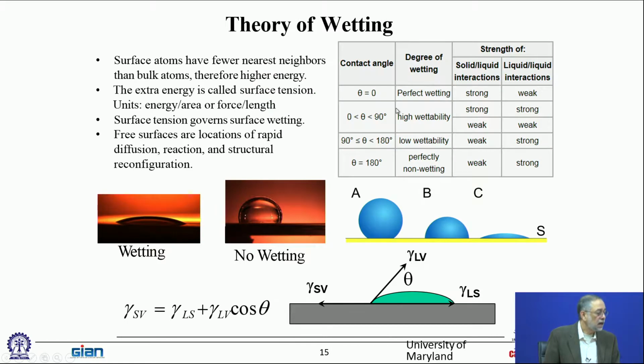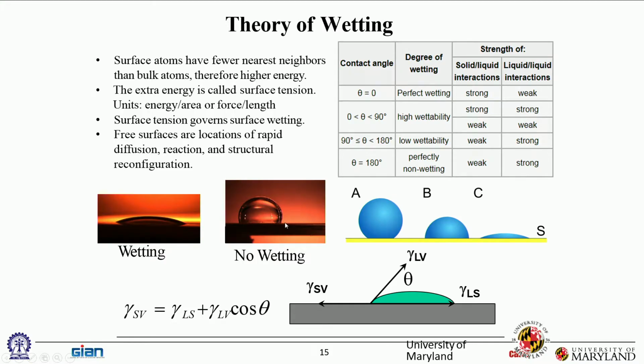Okay. Wetting. We talked a lot about the fact that you have to have good wetting. And here's a poorly wetted surface. Okay. And wetting basically comes because there's intrinsic surface energy. All materials have that, and that's because if you look at the nanoscale, the molecular scale, atoms at the surface have a different set of neighbors than atoms in the bulk. They have a different set of neighbors. So as a result, the energy of atoms on the surface is different, and that differential energy is what we typically call surface energy.